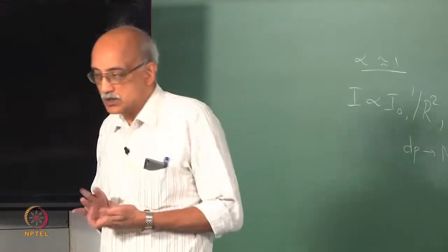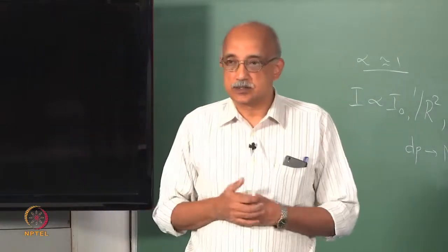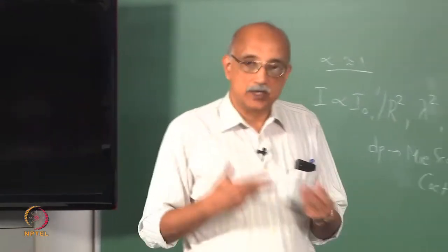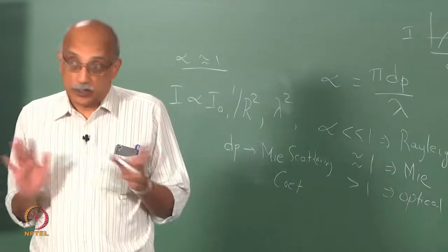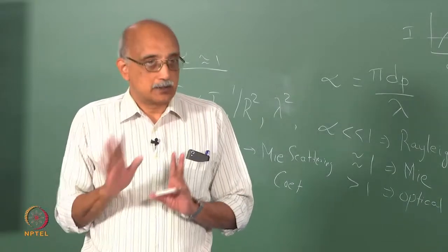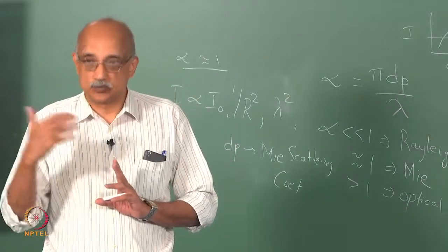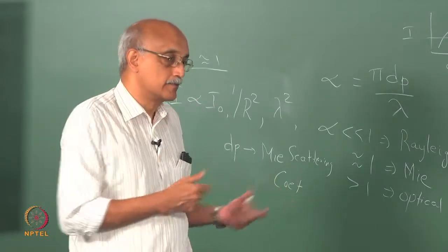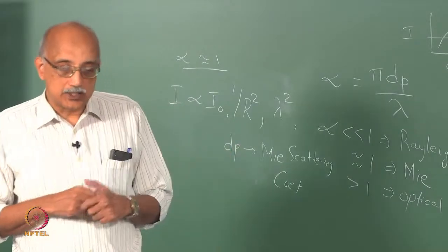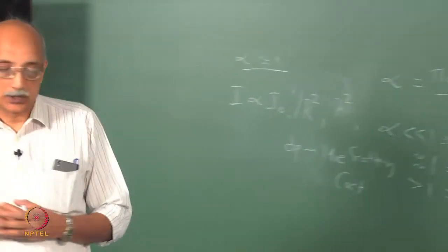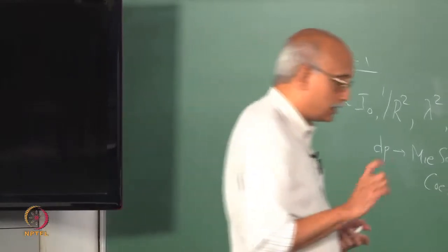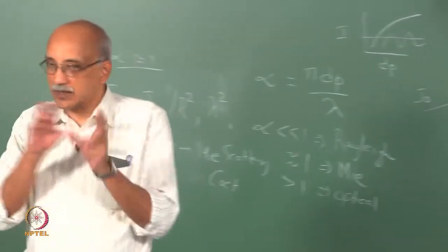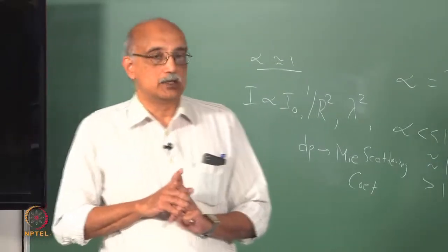So, size measurement, even though it is fairly easy in the larger sizes, in fact some of the methods you will be doing in the mechanical operations lab like sieving and sedimentation and so on are very good methods for particle size measurement, but for particles that are larger than about 40 microns. The challenges really are there when you try to measure particles that are finer, and light scattering is certainly a great technique to use, but you have to interpret the data carefully and you have to use some tricks once in a while to get particles to be in the right size range for you to be able to measure them accurately.